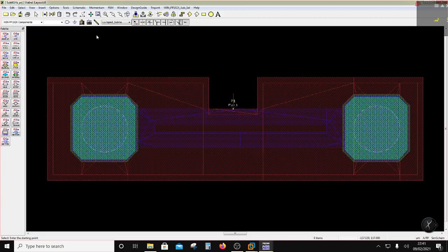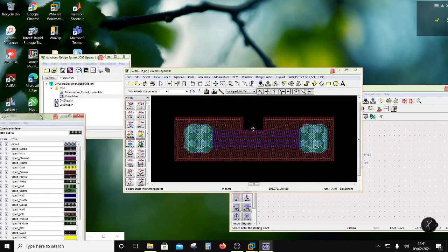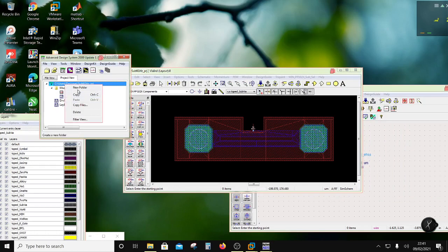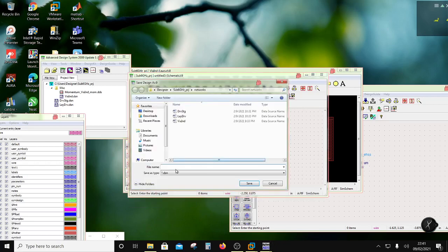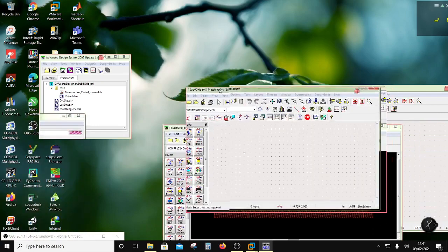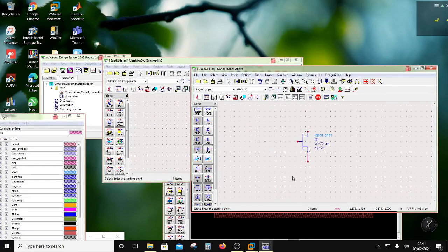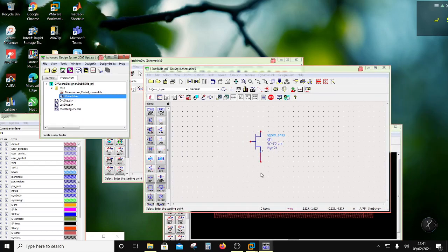So this is there. Now once you do this simulation, you can generate a lookalike component for this, and then what you do here is you create your schematic, and you say file save design, and you save this design as matching DRV, for example. So I'm going to do a driver stage matching. Okay, so now the question is, I have got two schematics here. One is over here. Here I will do the DC. Okay, so let me bring that component over here.